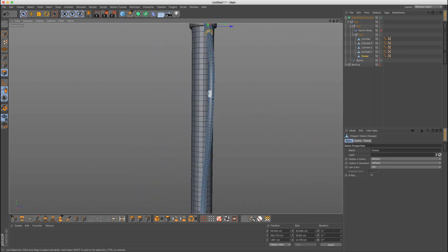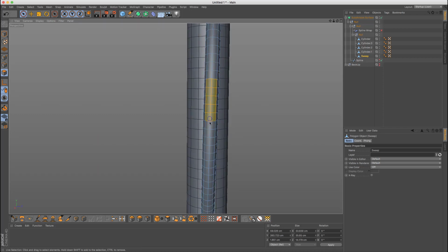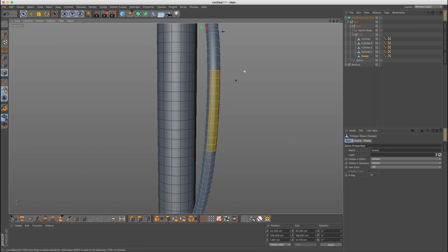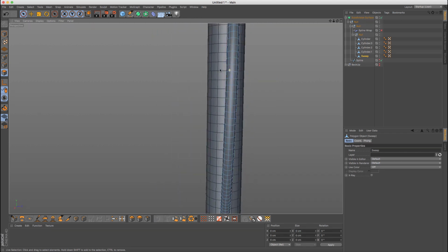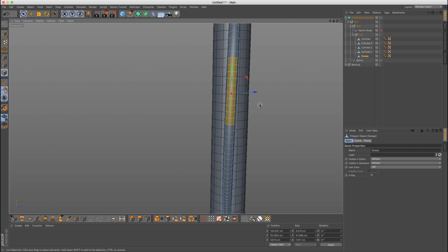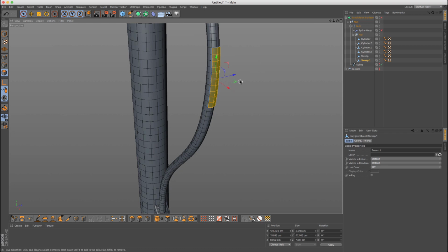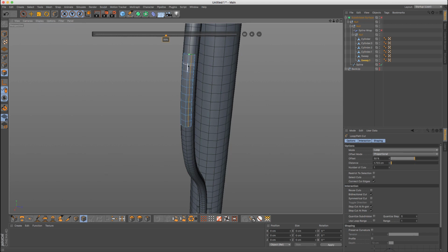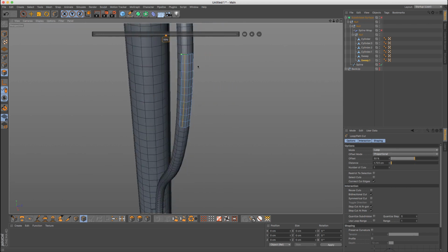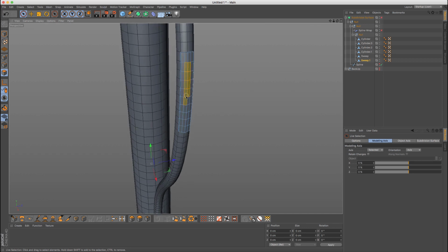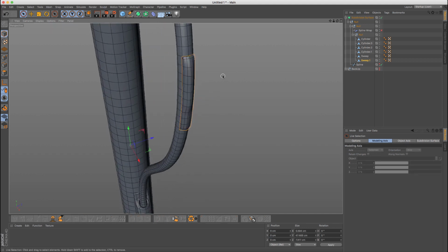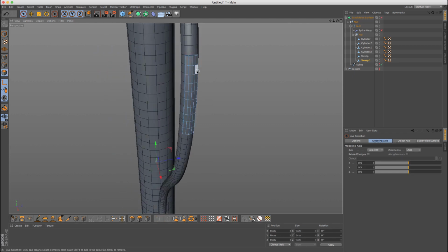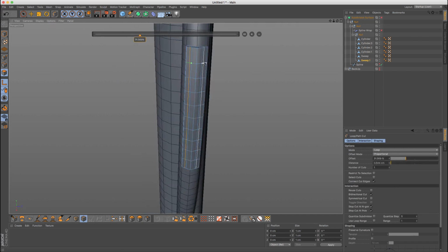Maybe let's come in the middle and select this middle point. And again, just make sure that nothing else is selected. So I'm going to use split again, and what I'm going to use again is small extrude, and let's add a few more edges here and here, and we can maybe simply push this out a bit. But maybe we're missing a few more edges, so let's add one more here and here.